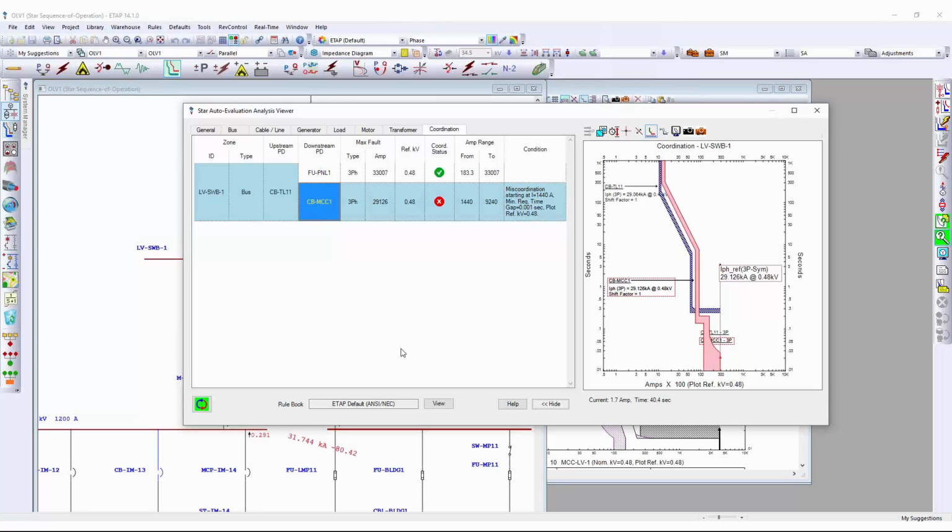If you want to run a study and make multiple modifications without rerunning every time you change one of these settings, what you can do is you can turn this auto run off. It means it would not evaluate and rerun the evaluation unless you're asking or pressing this button. Notice the green color. It shows that the tabular section is in sync with the graphical section.